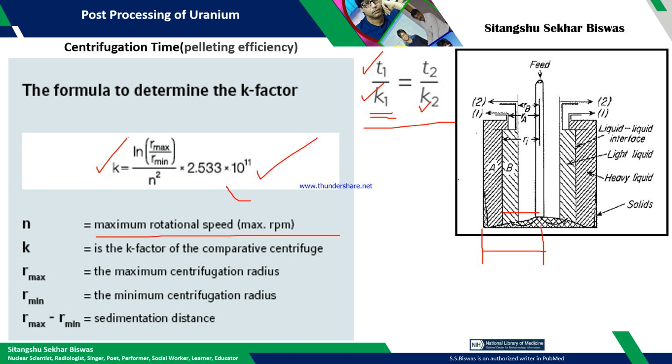Once the inverter is operating at very high frequency, it will increase the conduction and the switching losses, so that heat is to be evacuated. The convective heat transfer coefficient or the heat sink design should be sufficient to evacuate the heat produced from the conduction and switching loss of the semiconductor device. You have to maintain the power quality. All these things are to be taken into consideration during design.